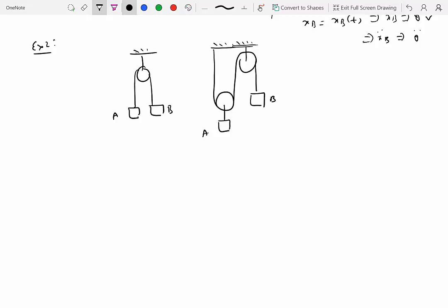If you've ever seen a crane out there in a construction zone, and if you look carefully, I know it's not easy because usually the pulleys are right on top and you can't see them very well. There are multiple of those stacked right on top of each other, and the rope essentially goes over multiple pulleys, and that's all because you want to reduce the load on the motor, which is going to pull the cable, which in turn is going to pull the load up.